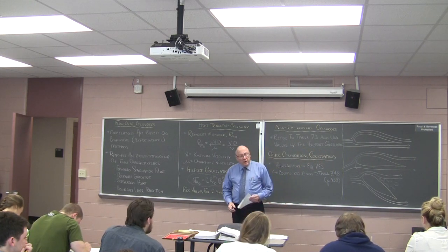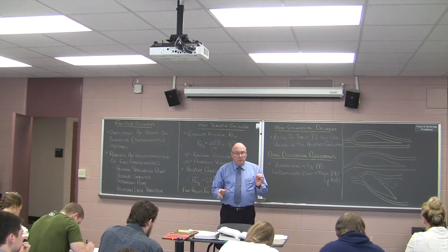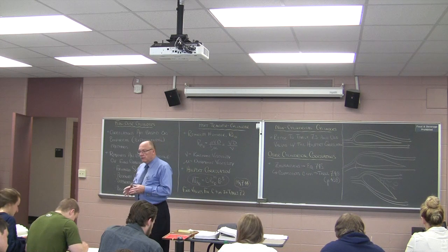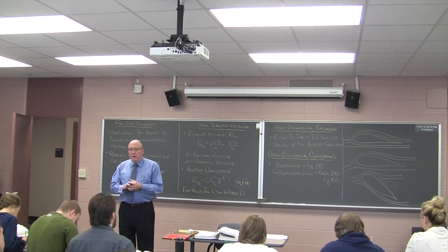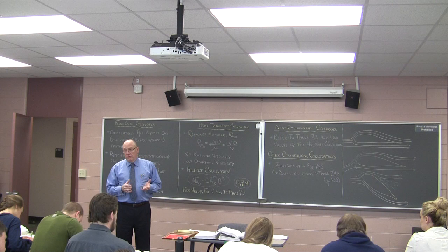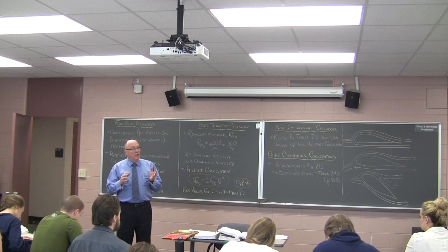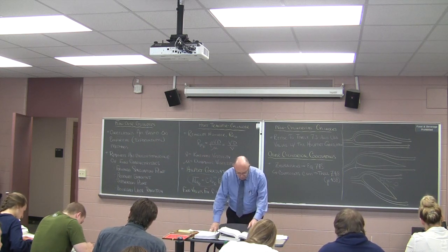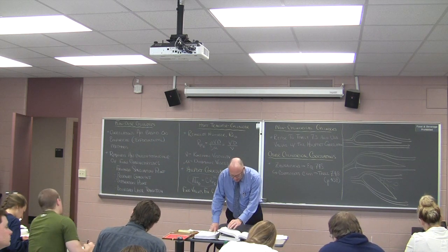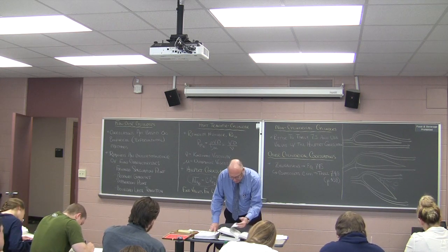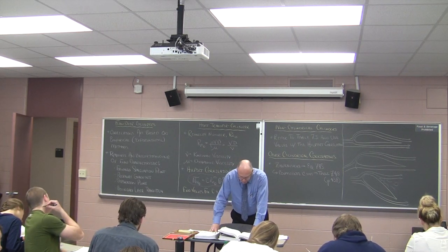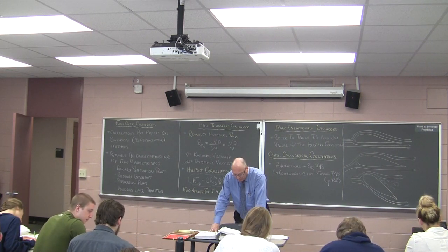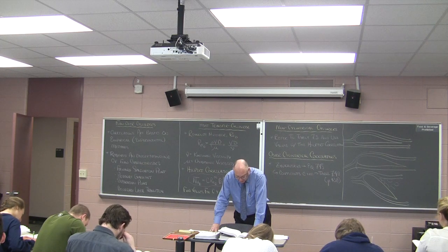Now, what is the primary difference in value of the Zukauskas equation versus the Hilbert equation? The Zukauskas equation allows for the consideration of the Prandtl number as calculated based on the surface temperature and related to the Prandtl number based on the fluid temperature. So if you go back to table 7.7 and look at the values, the Zukauskas equation has a wider range of Reynolds numbers, from 1 to 1 million.